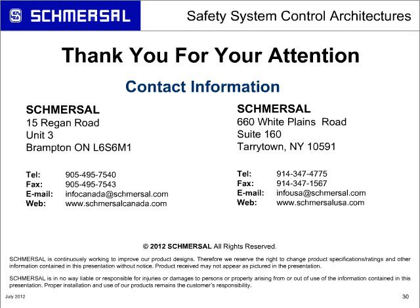But because that lock becomes a safety function, you do need that second switch on there to determine whether you had a catastrophic failure of the safety system with the mechanical key, because in that one instance, even though it may wind down to a stop, if somebody forced that open and you had a separate failure with a key breakage and that lock stayed locked, you can see the second switch determine that the lock has failed, and you can shut the machine down safely and prevent it from restarting.